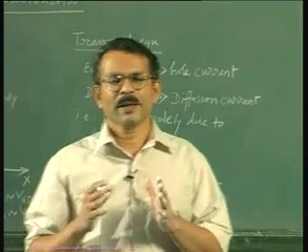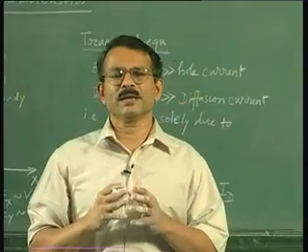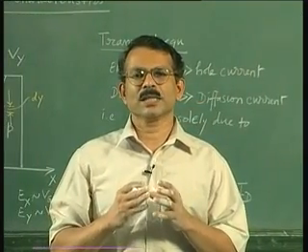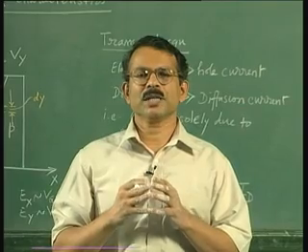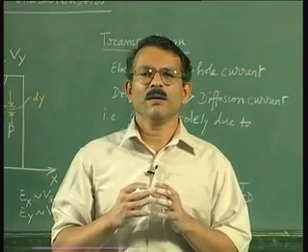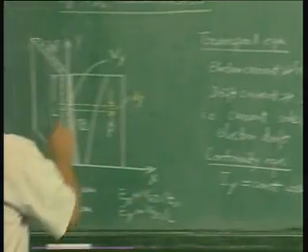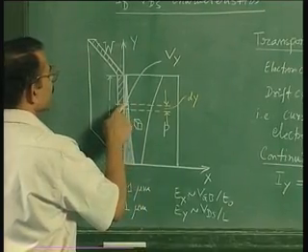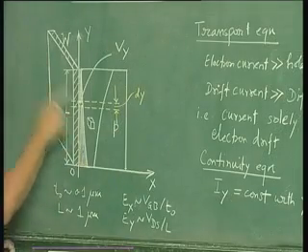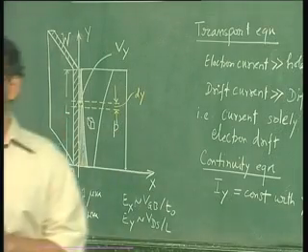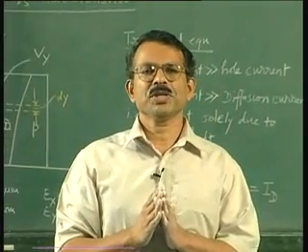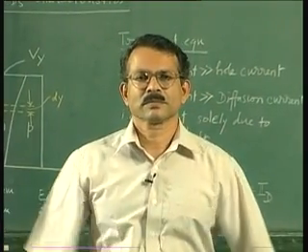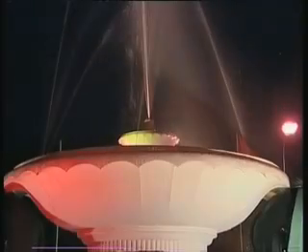Now putting these results together, we will show in the next class how an equation can be derived for the charge as a function of voltages at any element dy at a distance y, and how you can integrate the result from source to drain to get the complete current voltage equation.